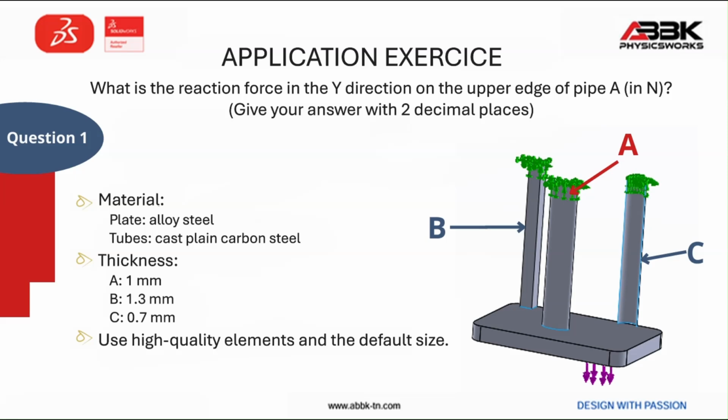Today's exercise will focus on analyzing reaction forces along with bonded connections. We have the material of the sheet metal and solid parts. We have the thickness of each sheet metal part. We will use high quality mesh with default settings.